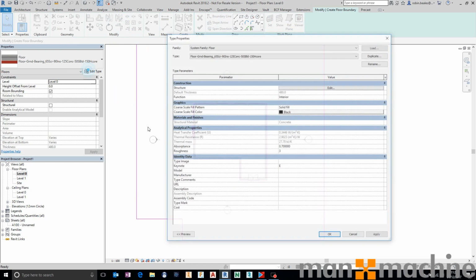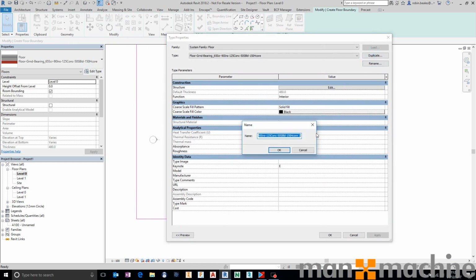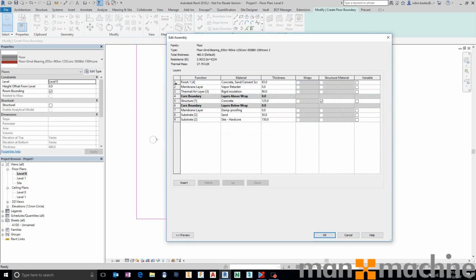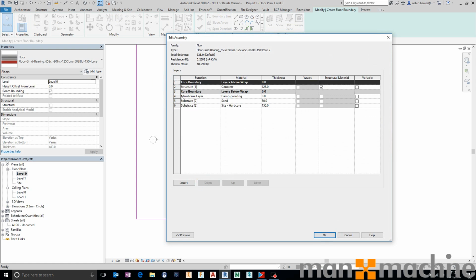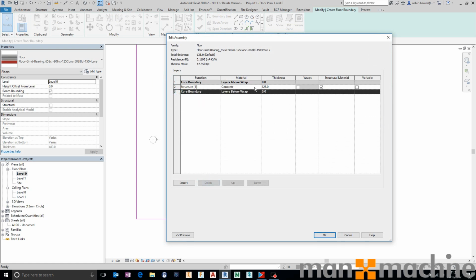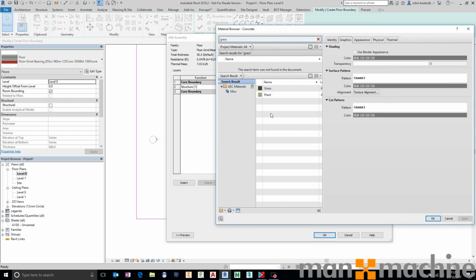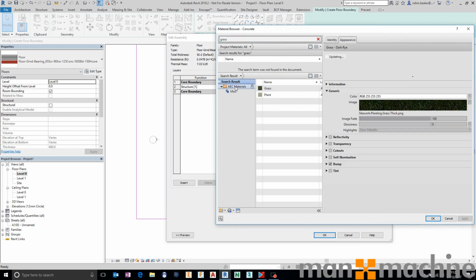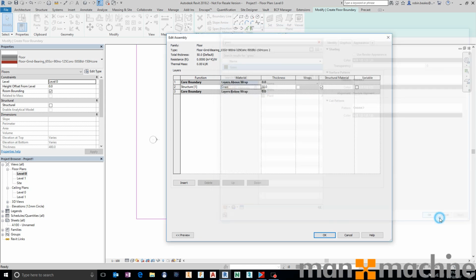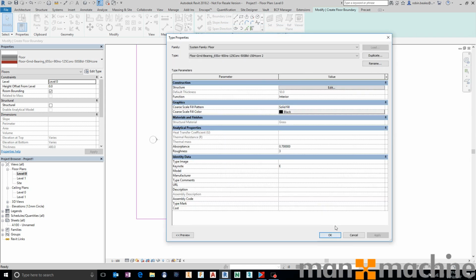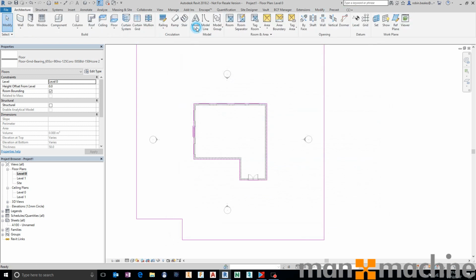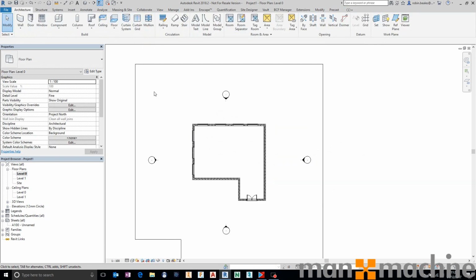And then I'm going to go in and create a duplication of this slab. Be very lazy and just take out all of the structure of that apart from the structural level. And I'm going to come in and use a default Revit material called grass from my default Revit library, my standard Autodesk AEC libraries. Pick grass, apply, OK. I'm then going to do exactly the same thing.